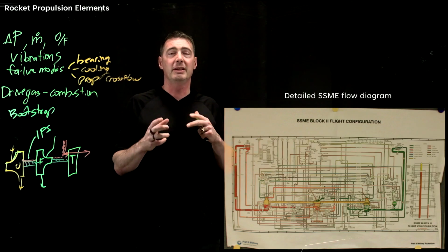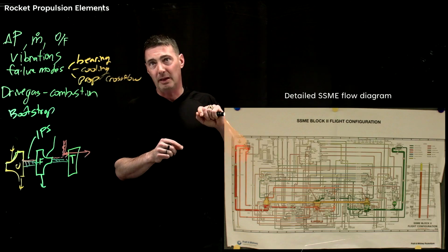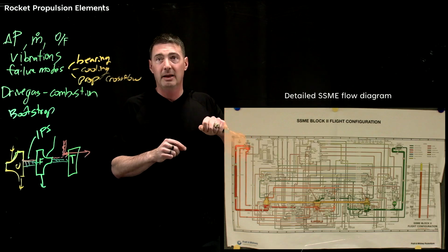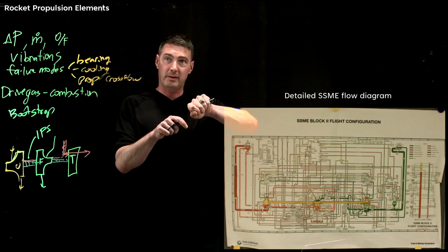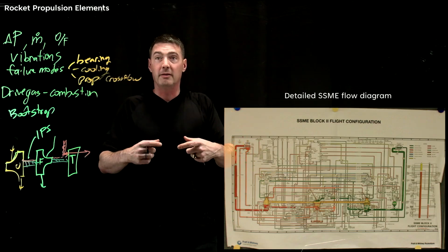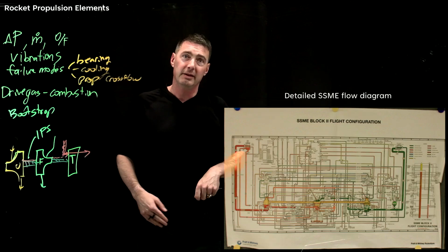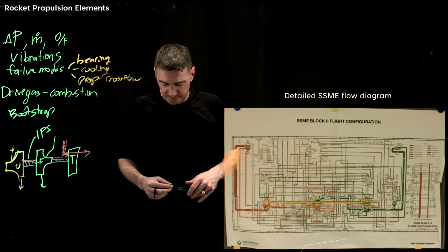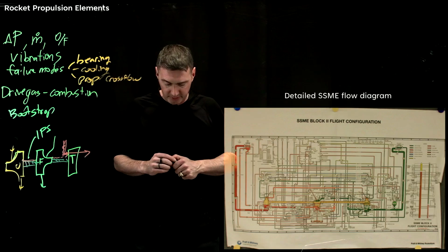Most valves are actually pneumatically driven from drive gas, and so you might be electrically piloted, which means you turn a valve to the nitrogen with an electrical thing because it's very small, and then that nitrogen drives a bigger valve, which is actually opening up your fuel valve or opening up your aux valve. So this can get quite complicated, okay, in a hurry.